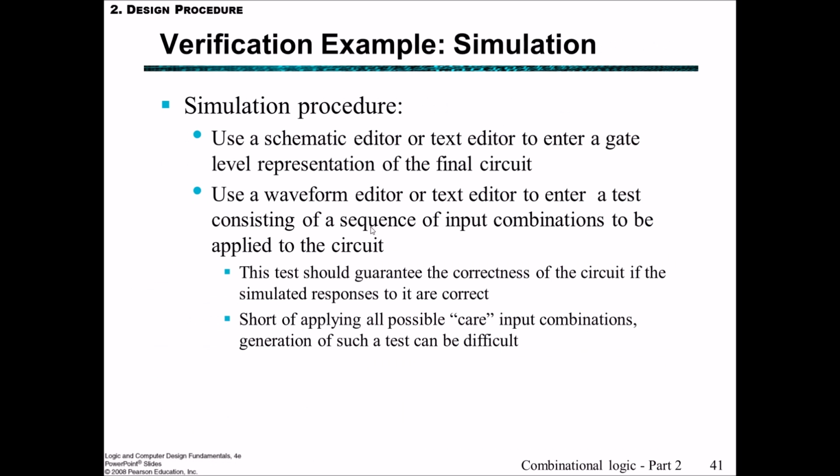We use the schematic editor in a program like Xilinx, or perhaps a text editor, to enter the gate level representation of the final circuit. And then we use the waveform editor to enter a test consisting of a sequence of inputs. That sequence of inputs would perhaps be the BCD inputs from 0 to 9. So this test should guarantee the correctness of the circuit if the simulated responses are correct. And we've got to make sure we test all the possible care input combinations, because otherwise it's difficult for us to verify the output for sure.